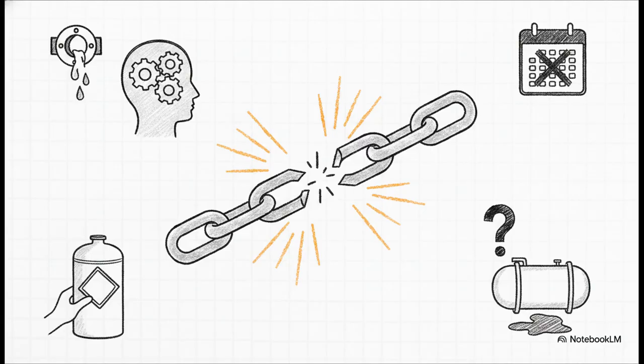But of course, every single stage in this cycle is a potential point of failure. The chain can break literally anywhere. At the depot, maybe it's just a missed gasket or some hidden pitting in the steel. At the plant, someone might accidentally load cargo into a tank that has expired test dates. Out on the road, a driver might prematurely peel off those dangerous goods or DG labels, completely breaking the safety information chain. And then at the gate, a surveyor might suddenly be faced with undocumented cargo residue. So, while the physical tank is brilliantly standardized, human error can still easily compromise the entire system.